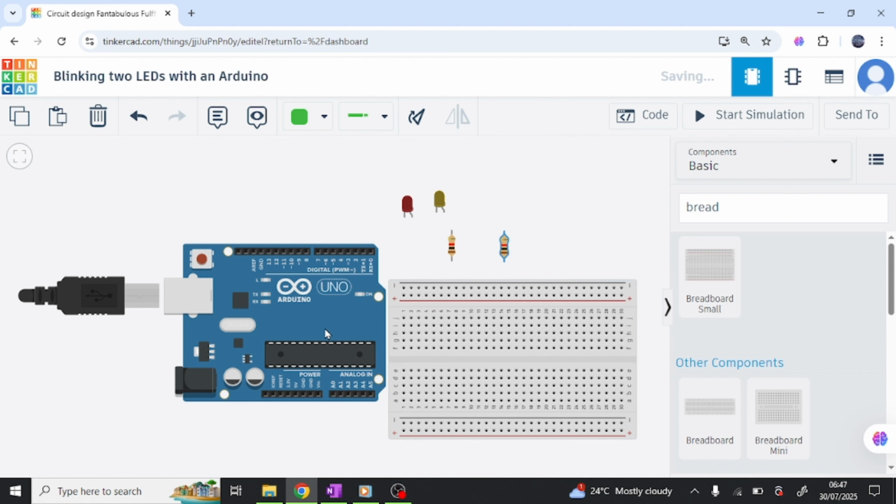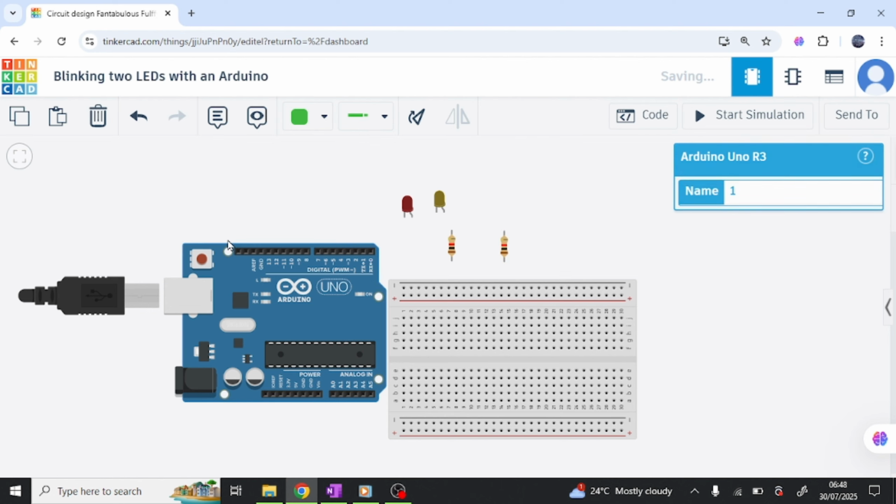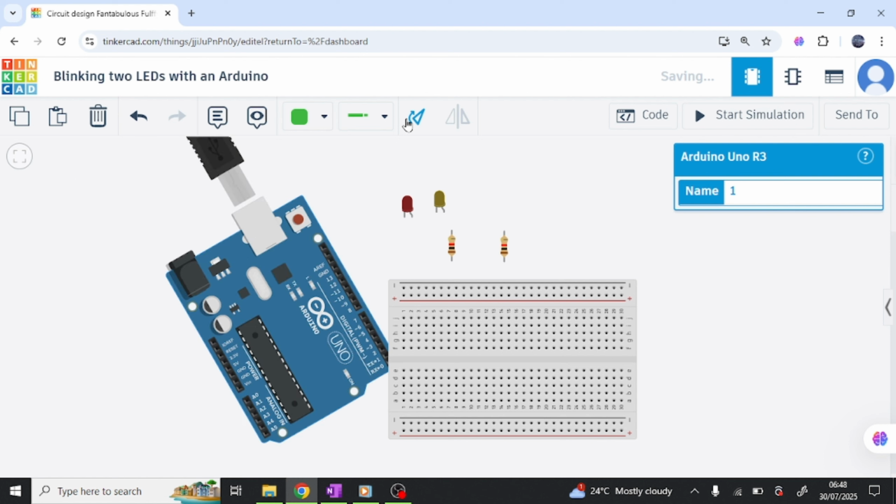It's just like an extension. So instead of connecting the LED directly to the Arduino microcontroller, we'll connect the LED to the breadboard, and connect the pin we want to that same line in the breadboard. You will see how we do that now. That's why we need the breadboard, like an extension of our connection. So let me rotate this so that we'll have more space, because I want to zoom in.